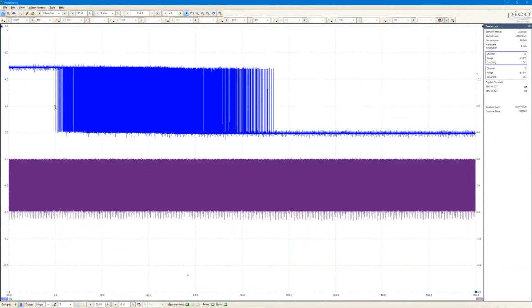We've got very often the situation where we've got a single shot event, a sequence of pulses in the case that I'm showing here, and we sometimes only get one shot at that event, but we nevertheless want to zoom in and in and in to see levels of detail that are really important to verify that the device that we're testing is performing correctly.